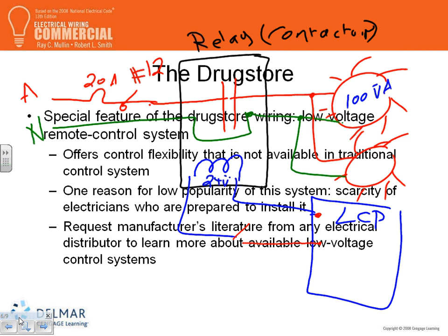So here's your low voltage switch, guys, and I'm just really simplifying it. This will also be fed from a 20 amp, 120 power lighting control panel, and when you close the switch, there is a transformer. Some of you will say, where did you, Chad, get the 24? The power comes over here, and a transformer, 24 volt.